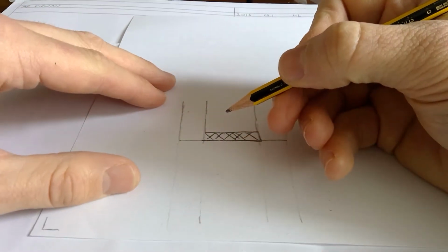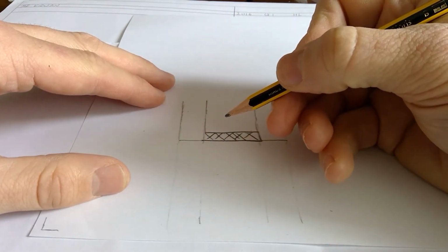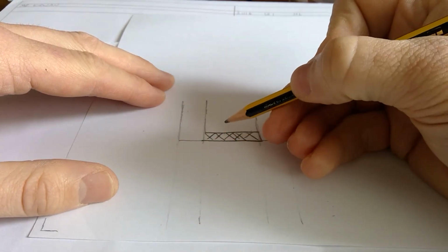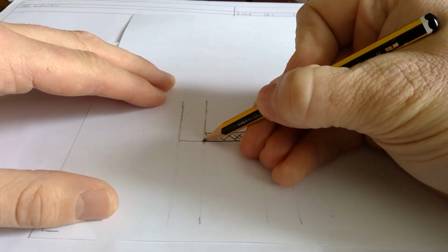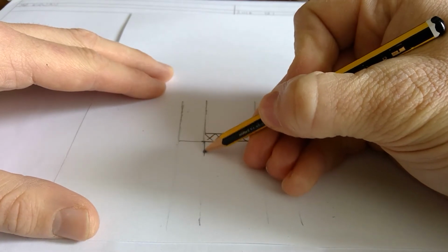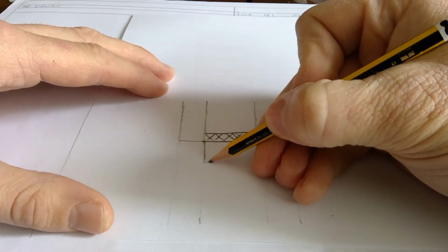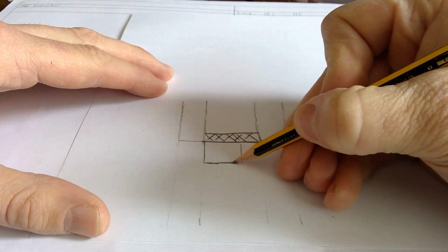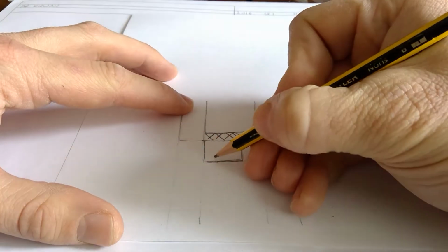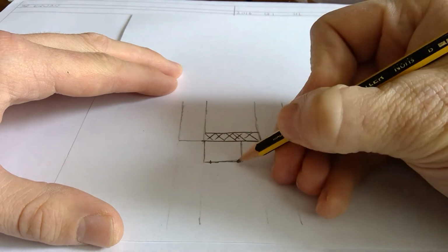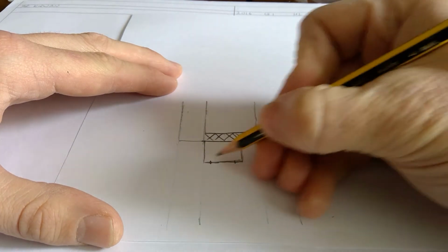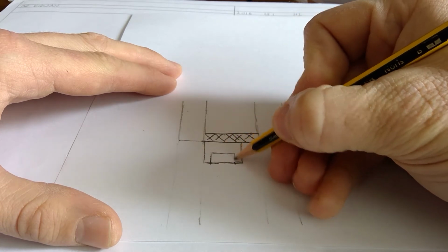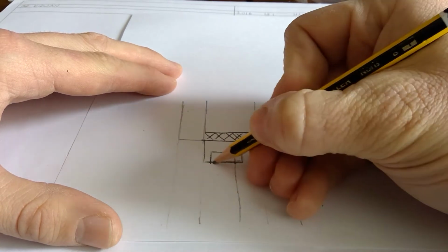Alright, now it says a triple glazed window with a thermally broken frame is fixed in here. It does not mention any sizes of a window frame, so we'll start at this point and we'll do our usual maybe 70 by 150. That'll bring us to about halfway across the cavity. So we'll go about there. Alright, measure in your approximately 5mm, whatever, an even space there. Go down about halfway through it and extend that down.